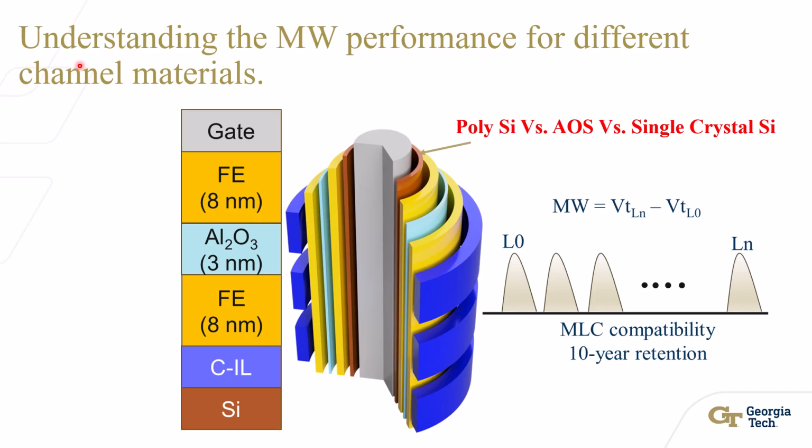So now let us try to understand the memory window performance for different channel materials for the same laminated Fe oxide stack. Again, a large memory window is always desired because it will help us to have multiple VT states to enable multi-bit capability.